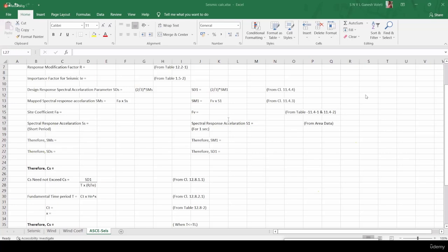I have got some chart here. Is 0.2 a constant coefficient, only for less than 5% or more? Midun asked me whether 0.2 is constant or any other coefficient. Just go to clause 7.3.2.2. You'll get some more coefficients for different types of openings. 0.8 is critical, and what point would we take if the value were minus 0.10 and 0.5?